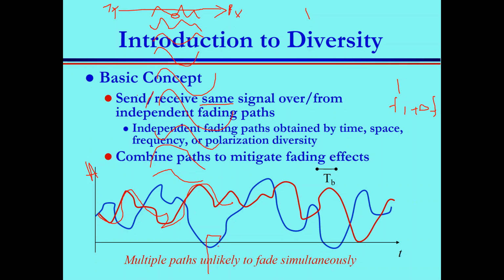So when you send your data over this channel, what happens? The channel acts like a filter. It suppresses it. When you multiply, for example, let's say this value is 5, and multiply it by the value of the channel here, 0.01, what's the resulting value? It's multiplication, yes, convolution in time, multiplication in frequency. When you send your data of amplitude equal to 5, meaning very high power, and it faces deep fade, the amplitude of the channel is 0.01. When you multiply them with each other, the resulting value becomes so small.